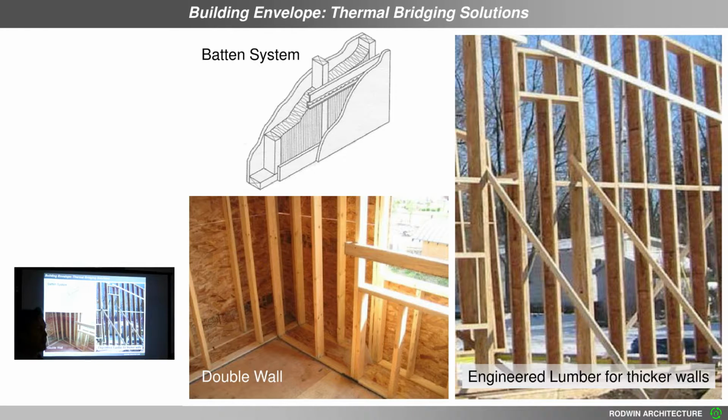And then you can fill it with cellulose or a blown-in bib insulation and fill up this huge cavity with one of the less expensive insulations that doesn't have as high an R value per inch, but you're giving it more inches. It tends to also create an old world, almost European look to it. But it does take up some square footage and adds to the cost because you're essentially framing two walls, one on the inside, one on the outside.